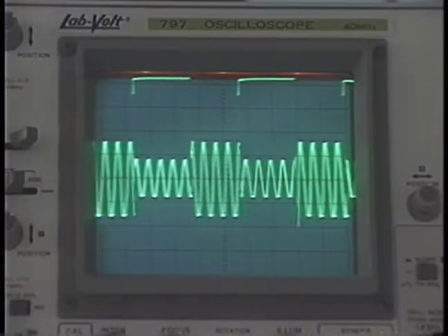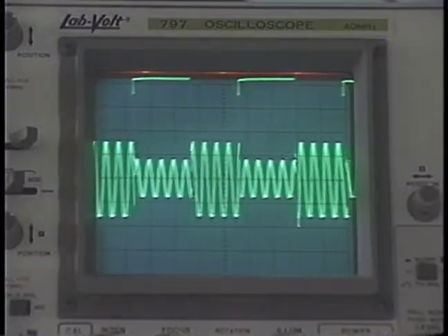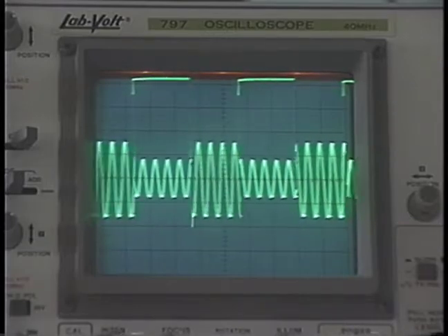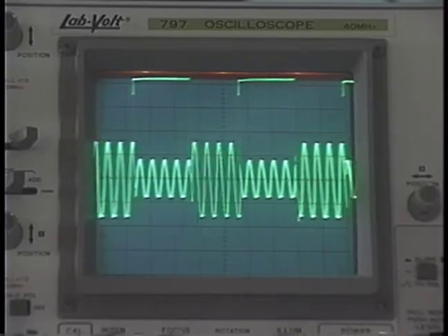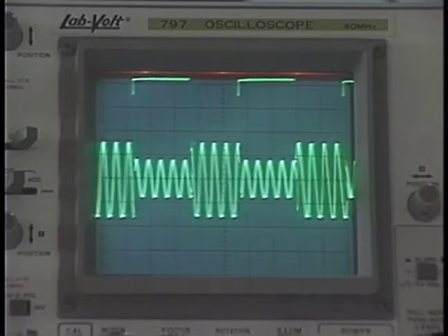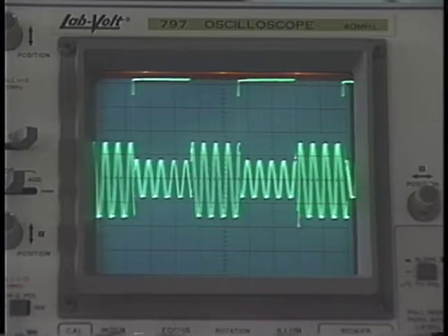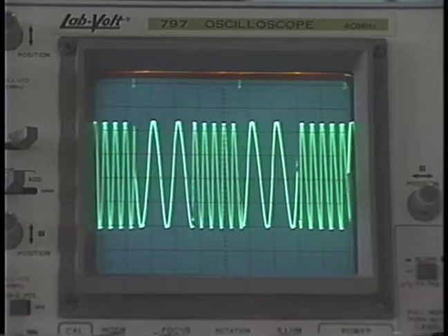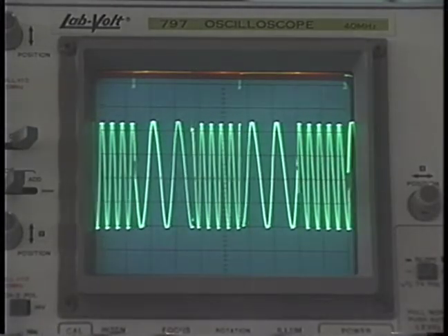Here we see a carrier signal that is amplitude modulated by a digital information signal. This technique is called amplitude shift keying. This technique changes the amplitude of the carrier to represent the digital on and off states of the information signal. Amplitude shift keying allows computers to communicate using analog telephone lines. A device called a modem modulates the signal. Another technique modems use to transmit digital information over analog telephone lines